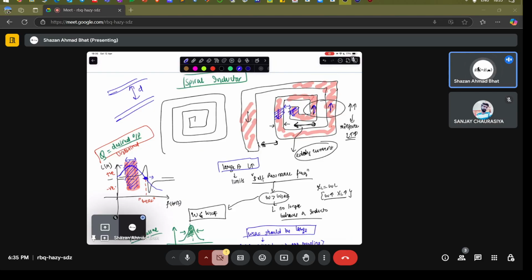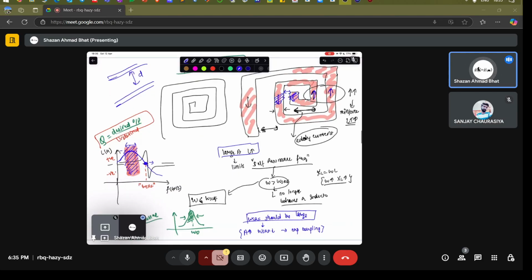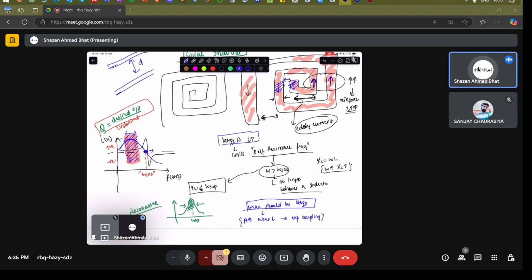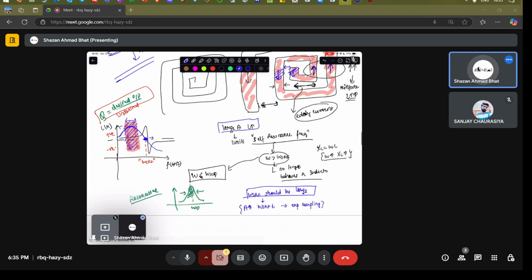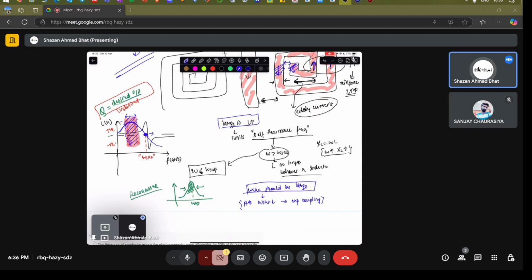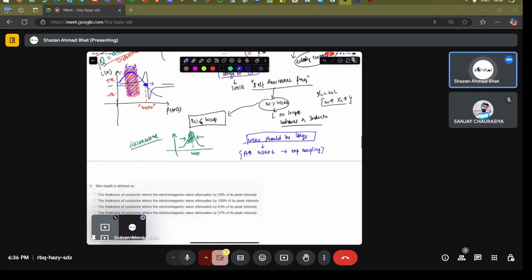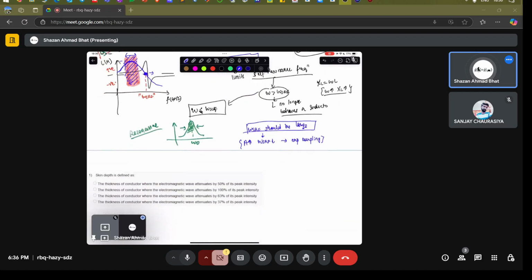And here we are talking about at a nano fabrication level. These capacitors are always there as capacitive couplings, but they don't come into the picture unless you go to a very high frequency. At that very high frequency, the inductance becomes very small, and the capacitive coupling comes into the picture and becomes dominant. Then it is dominated by the capacitive coupling, so that this becomes negative, and you have a huge capacitance coming into the picture.